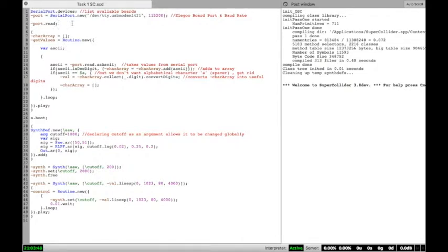The port read just tells you what single numerical data is coming through, as in the character, and this data is stored within a current rate. So this routine here basically takes values from the serial port, the raw data that is, and basically takes the ASCII data and transfers it into raw numerical data, just to try and get a purer form of data, seeing as you can't really use ASCII characters too well as a controller within Supercollider.